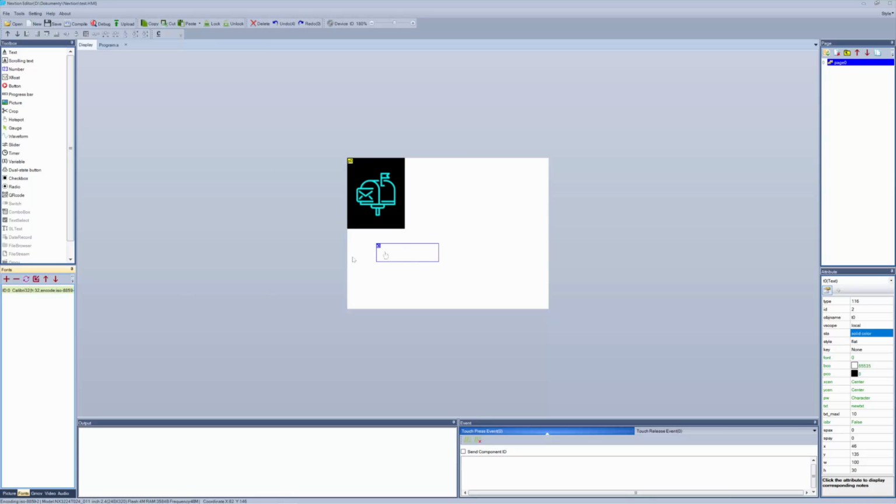And once you do that, you reference this font in this object. It's already referenced because 0 is there by default. So I have font ID 0, and here's the text. If I change this, it will change the content of the box. And this is how we will actually interact with the display from within ESPHome. We can change the text property of this object. This is object ID 2, and it has a text property AAA. We can change that, and by doing that we will display different text.